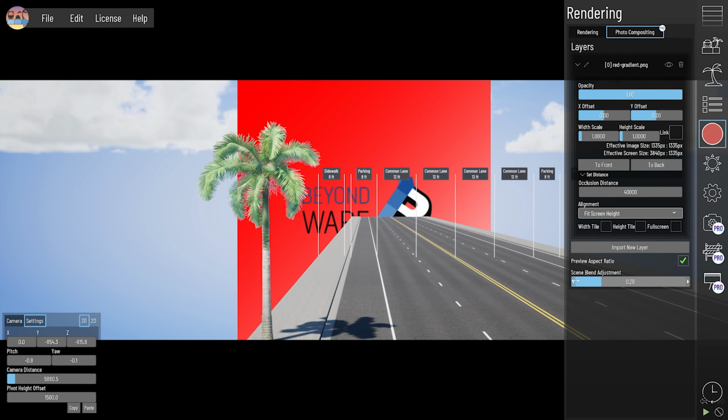The most important image setting for the next step is the opacity setting. This spin bar allows you to adjust the transparency of the image, which will be vital for lining up your Beyond Typicals model camera with the imported image. Finally, in the layer list, there is a pencil icon that allows you to rename the image layer. There's an eyeball icon to the right of the layer name that can be used to hide and show the image layer, and a trash can icon to delete the image from the model.